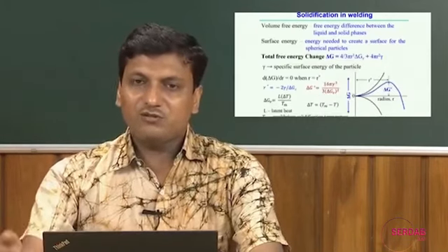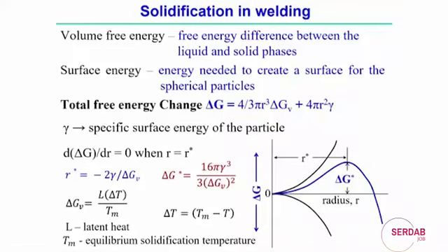Now, if you look a little bit into the theoretical aspects of this nucleation process, it will be more beneficial to understand the solidification process in welding. So, we try to bring these two things together. So far, we understand solidification in a simple way: there is simply a change of phase from liquid to solid, which may happen at a single point temperature, or over a range of temperature, whether it is a pure metal or some alloy system.